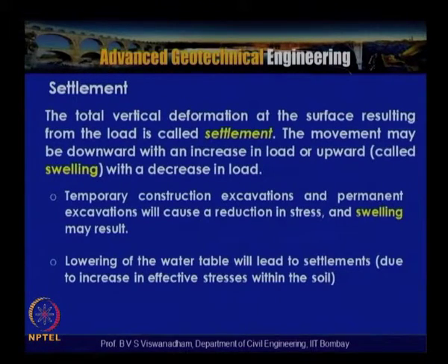Temporary construction excavations and permanent excavations will cause a reduction in stress, and swelling may result. Lowering of the water table will lead to settlements due to an increase in the effective stress within the soil. So in this slide, what we are trying to determine is the settlement.